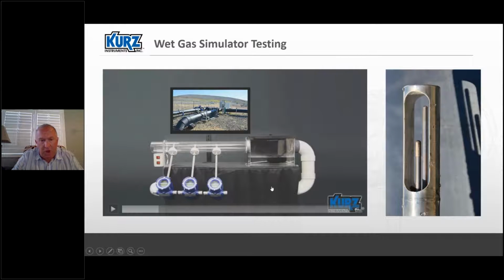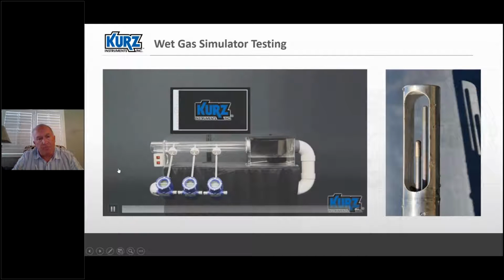We have a small supply fan here, and we have an inlet flow meter here as the reference dry gas measurement. Here I have a small tank of water and a little disco fogging device that'll throw a lot of water in the air, trying to simulate condensation in the line. Let's see how this proceeds.